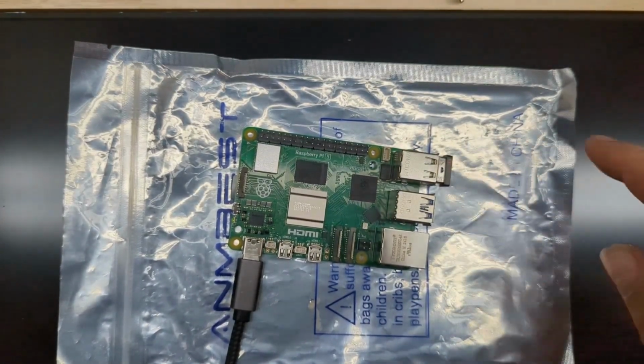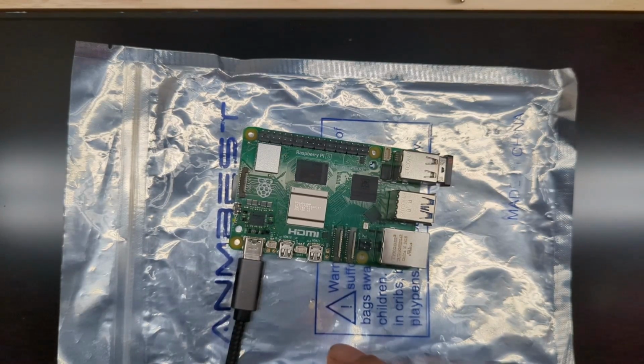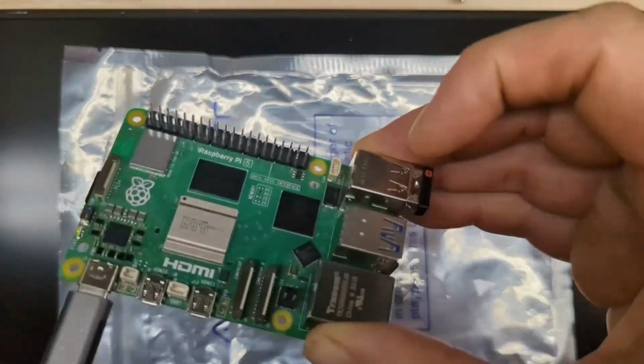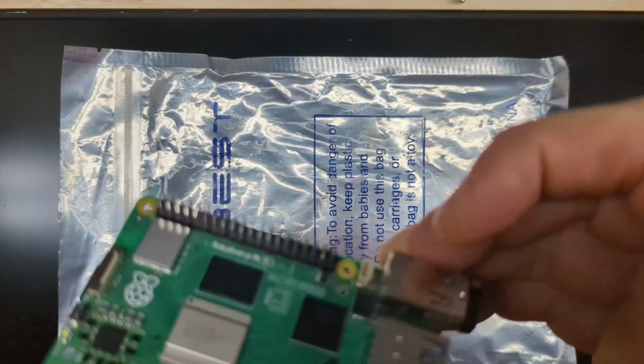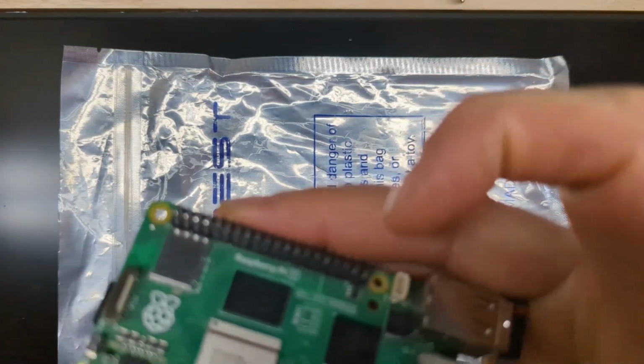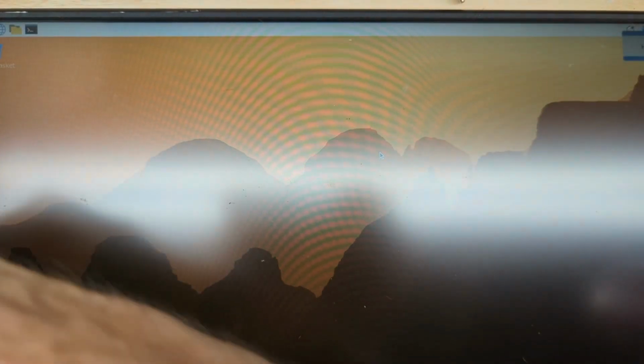And then we have this monitor that's sitting right below this. It's just an HDMI connection on the monitor. You have an HDMI output on the Raspberry Pi. You just have to make sure you have the right connectors, because the Raspberry Pi HDMI port is a micro HDMI. So we will go ahead and connect the micro HDMI port, and then make sure you have the connector facing the correct direction. Push that in. And then you see the monitor just lit up behind it.